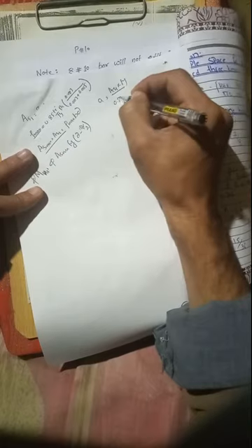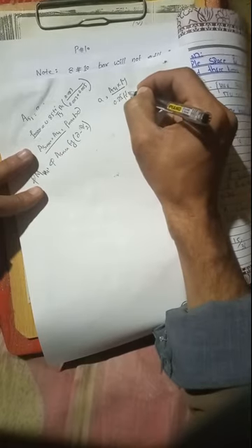After that you find the moment capacity, phi Mn1, that is phi times As max into fy into d minus a over 2. From here you calculate the value of a. a is equal to As max, or As1, times fy divided by 0.85 fc prime times b. So we calculate the value of a, and you find the capacity.